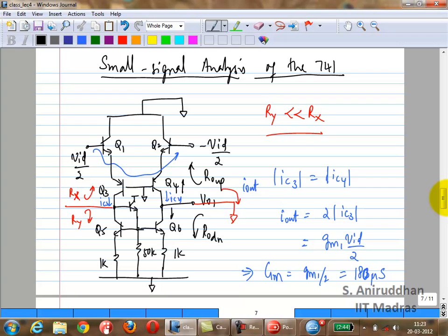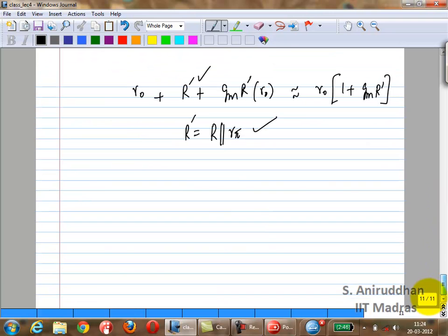In this case it's more straightforward. So just calculate the overall R out. Good question. Keep track of which R out you're changing, right? Keep track of whether it's RO4 or RO2, because Q6 is an NPN, Q4 is a PNP. I'll give you the VA numbers. Assume that the early voltage is 130 volts for your NPN and 52 volts for your PNP.